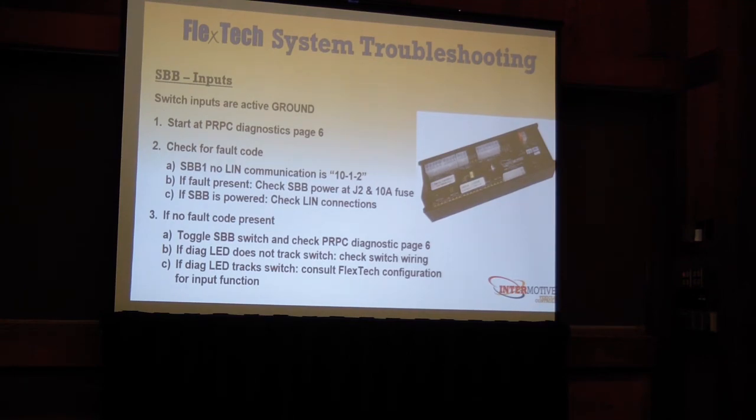Once again, an issue with a switchback board input could be due to link communication issues, could be because the SEB just doesn't have power, or it could be an issue with your switch wiring.